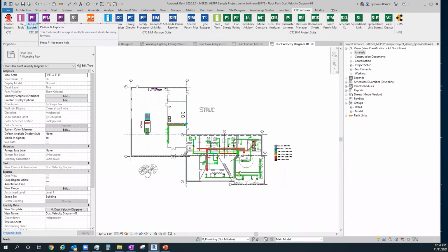And it does have a tool in there for a Windows-based scheduler, which means if you have the machine turned on and logged in, then Windows can run a schedule at midnight or some other time and have that done. So you'd have, say, PDFs done for the morning. Come in and validate that all those PDFs generated correctly, and then go back and maybe fix a couple extra sheets that we still had some troubles with. Take those, make them PDFs, put them in the batch of the set, stick them in Bluebeam or something like that, put them all into one big PDF file, and then send it out. So it can give you a lot more time if you have large projects to process.